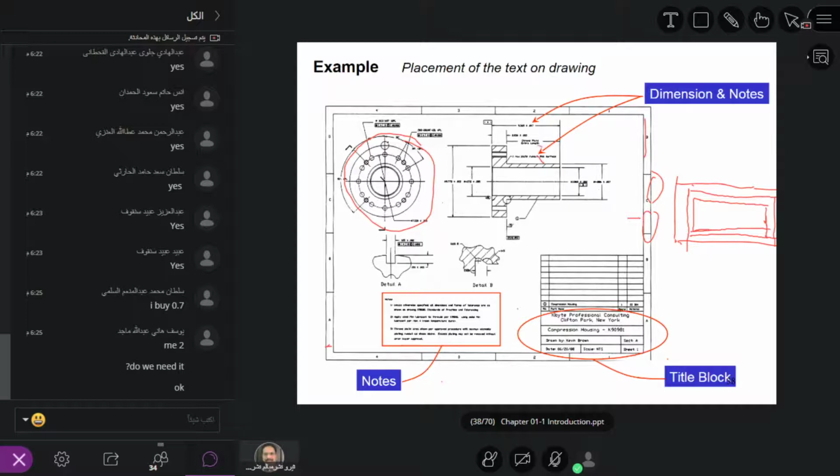Okay. So the margin, and then this is the drawing with certain views, and we will learn it later. This is the cut sectional view, and this is why I told you there are several views, sectional views. Here are some of the instructions and notes. The title block has the name of the drawing, the type of drawing, the number, the metric, the materials number, everything. So about this particular drawing, the details are here. It's like naming, like everyone has a name. So this drawing also has a name, and other details are given here.